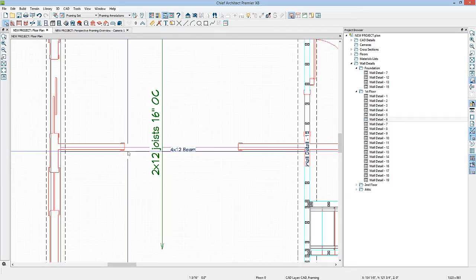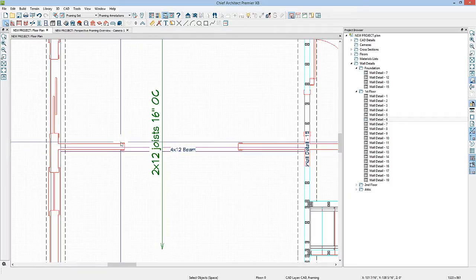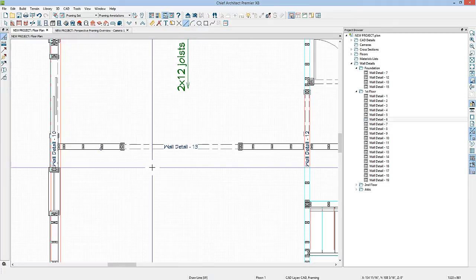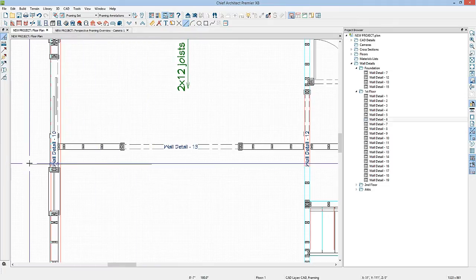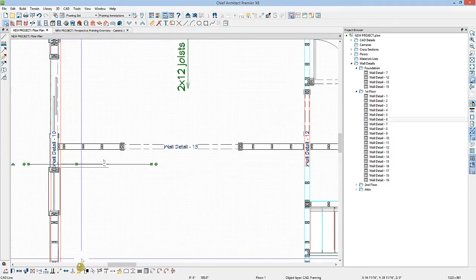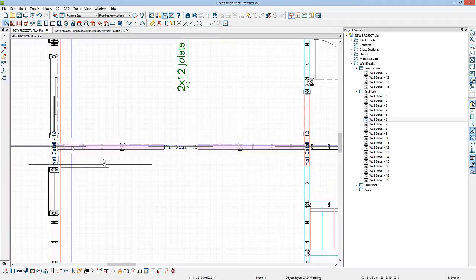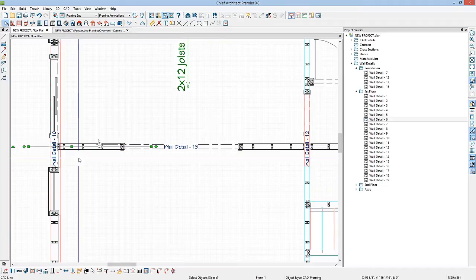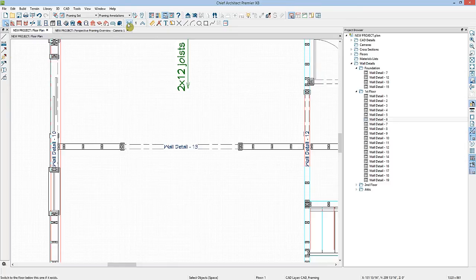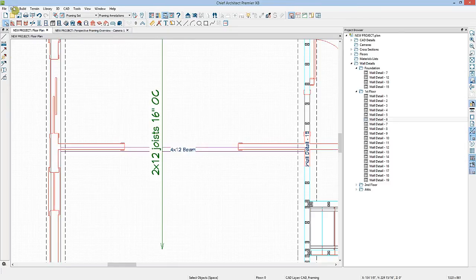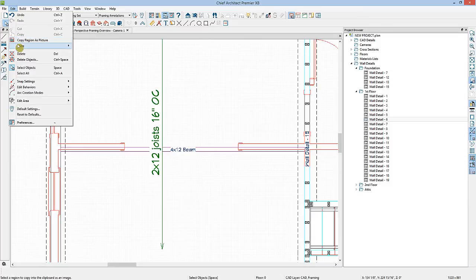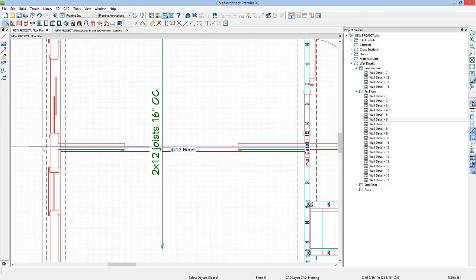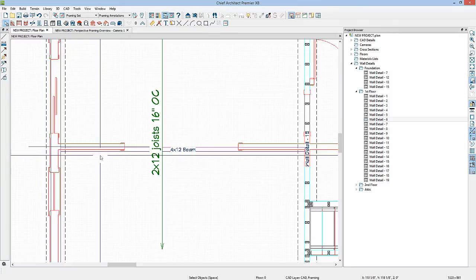And now I want to center this beam on that first floor wall. So I'll go up to the first floor level, and then I'll draw a construction line. Then I'll select the line, and then center it on the wall. Now I use my copy and paste tool. The hotkey for this is to hold down my Control key, and here I'm going to hit the X to cut it from this floor, and then I'll go down to the foundation level, go up to the Edit drop-down menu, down to the Paste menu, and Paste Hold Position. It'll place that construction line in the exact same place on the foundation level.